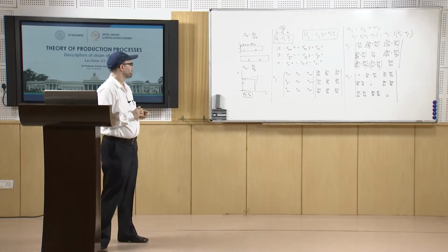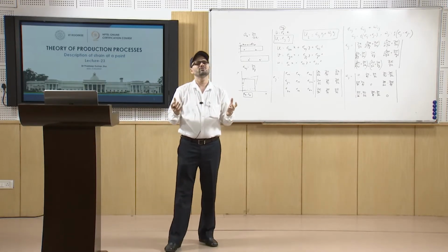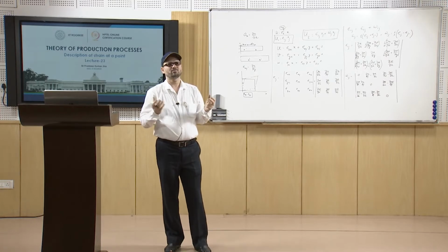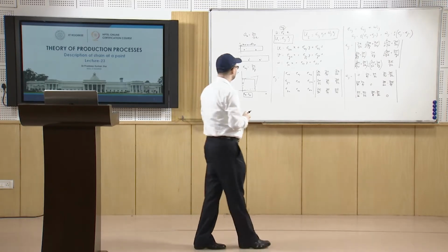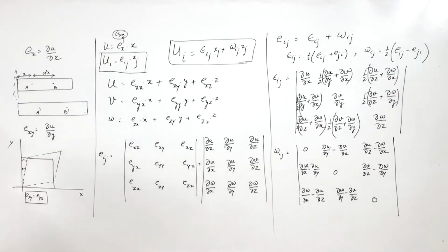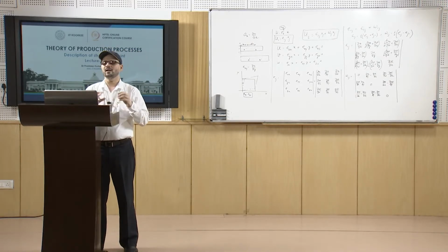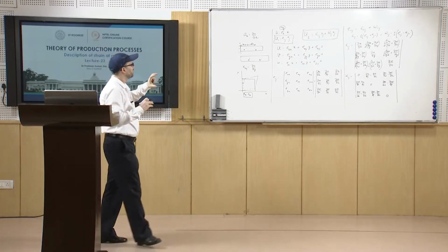So that will be Exy plus Eyx, that is ∂u/∂y plus ∂v/∂x. In the case of pure shear, you have this and this coming together, so that will be gamma. So that way you define the shear strain as total angular change from a right angle.